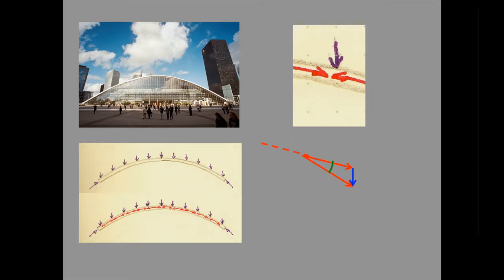Something that is also significant is that because the internal forces are increasing down towards the foundation, the lengths of the arrows representing them also increase, but the load arrow remains the same because the load is uniformly distributed. This means that the further down the shell that one goes, the smaller is the angle between the two red arrows in the vector diagram, which in turn means that the change in direction of the shell required to preserve the axial internal force only condition decreases.